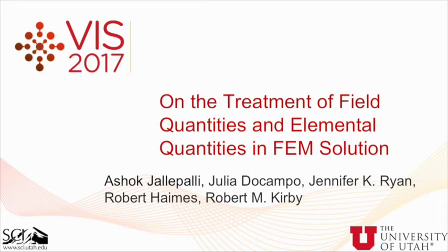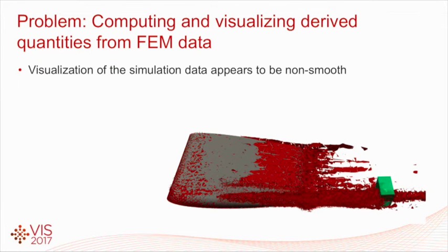Good morning, everyone. In today's talk, we approach the problem of computing and visualizing derived quantities in FEM simulation data. This is the visualization of data from the simulation. What is the problem with the visualization? The data looks non-smooth and inconsistent with the physics. The reason the data looks non-smooth is because of the discontinuities.